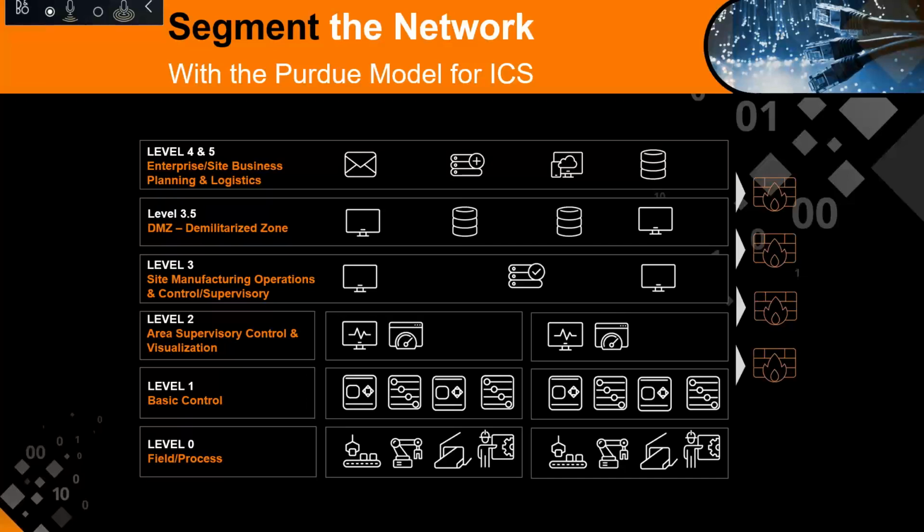And this basically is the first thing that you can do yourself to increase the cybersecurity level of the industrial network. I'm sure most organizations have a firewall, right? So if you put the industrial network on a separate physical interface on that firewall, then at least there is a separation between IT and OT. And even if you put a statement on the firewall to allow all traffic, but at least monitor it, you will have a gain, really.